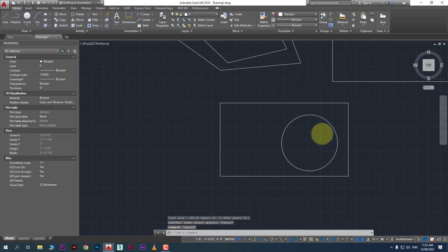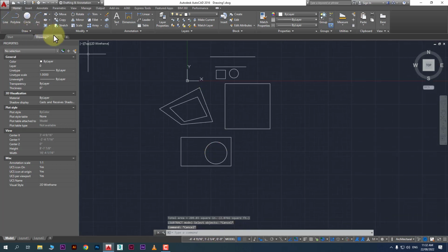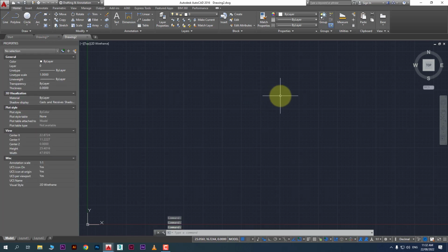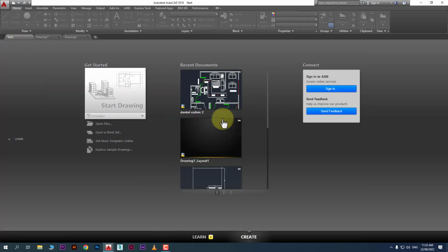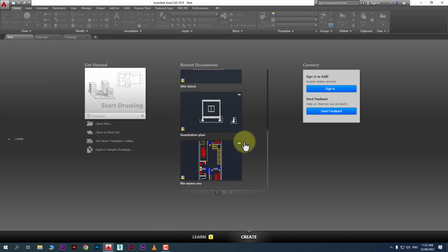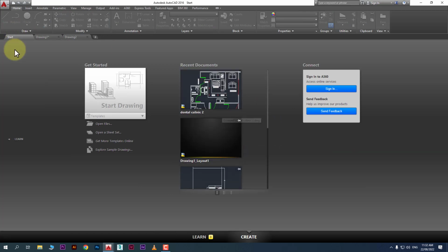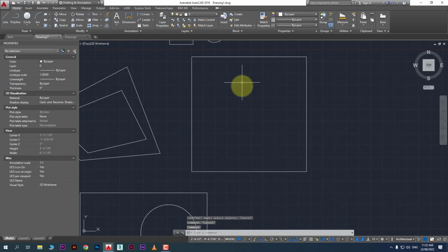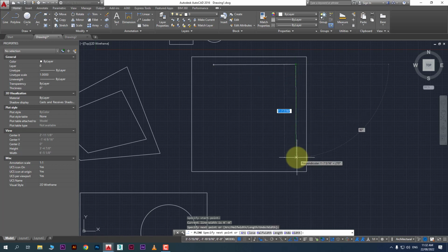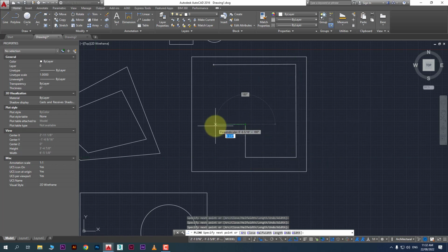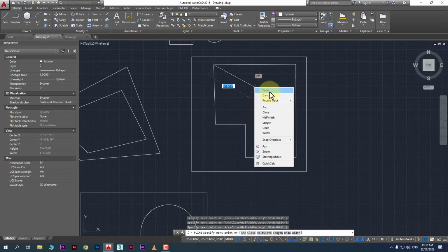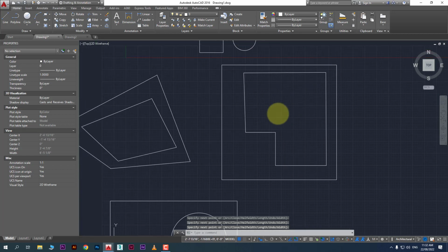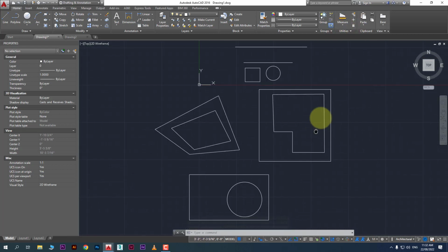You can also perform it like this if you are building a house, for example. Let me see if I have covered and uncovered area in my drawing. Right now, for example, I don't have it. So you can measure like this. For example, that was your total area. Then you make a polyline and you build the house like this. You have to tell the client what area you have used and what area is covered. So again, follow the same procedure.